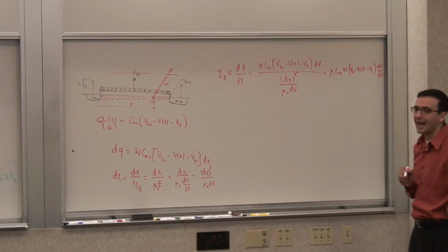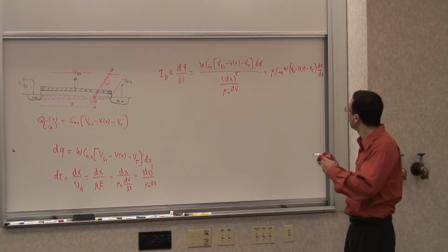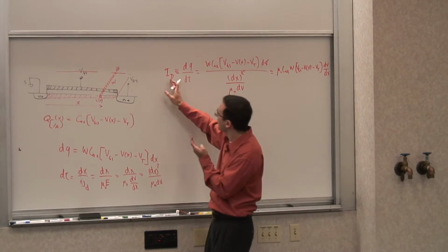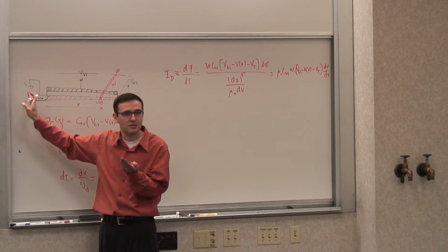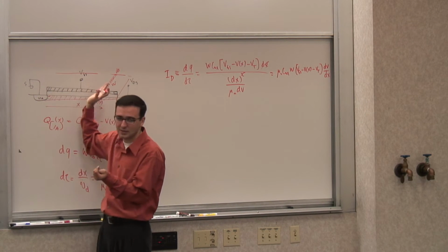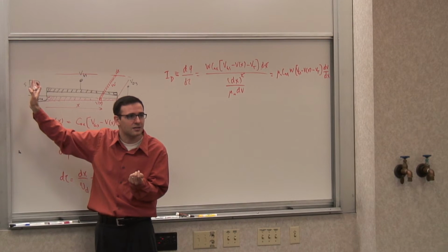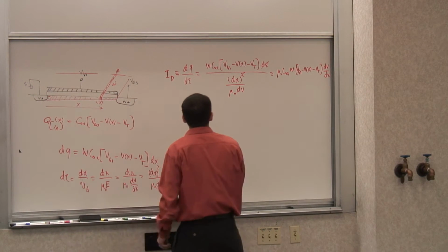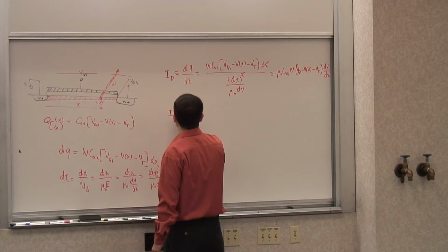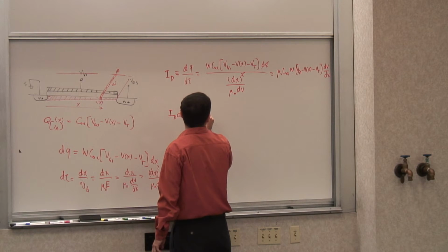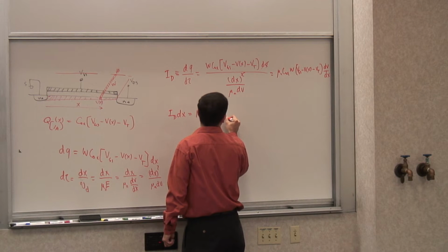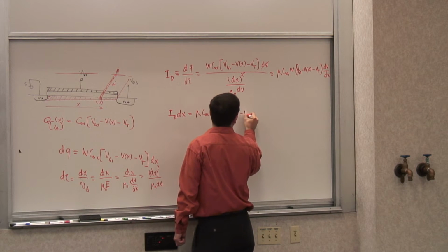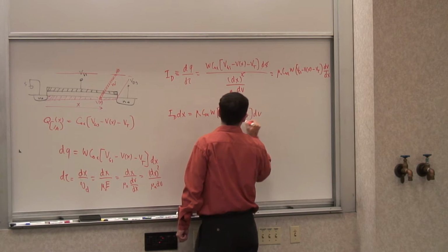So what I really want to calculate is the current in the transistor in terms of the voltage drop across the whole transistor, the big transistor, which consists of an infinite number of these infinitesimal transistors in series. So I can rewrite this as ID dx is mu n Cox W (VGS minus V of x minus Vt) dV.